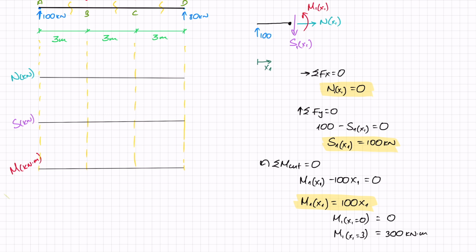The other thing that I need to consider with a moment is where I draw it. I can draw my moment here on this side of the beam, or I can draw my moment here on this side of the beam. In the UK, it is pretty important for us to always draw this on the tension side. There are reasons for it, and I do discuss this in the lecture, but drawing on the tension side, in short, gives me a very good indication of where I would reinforce concrete, for example, and a good indication of the deflections of the beam. Both are pretty important when it comes to design.